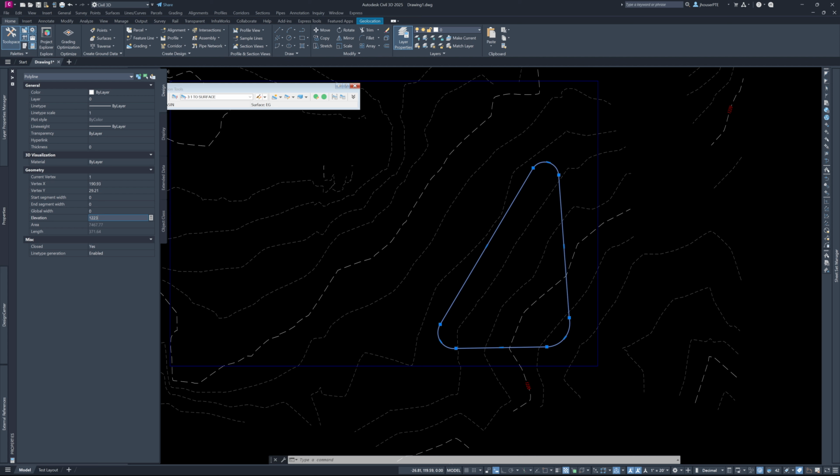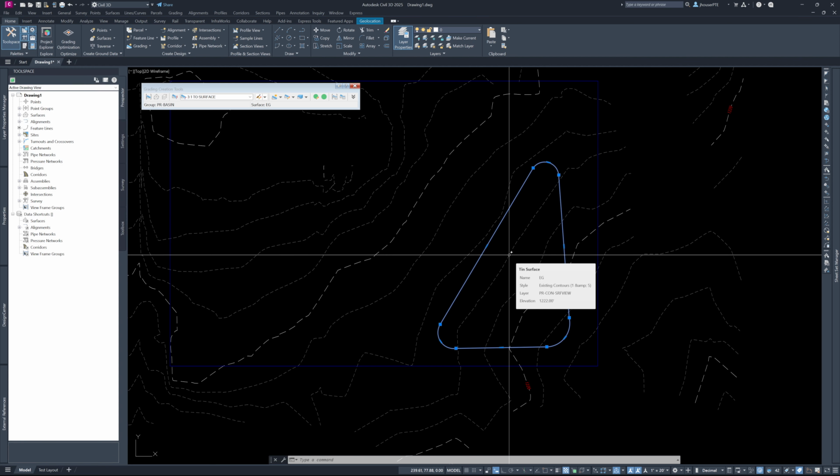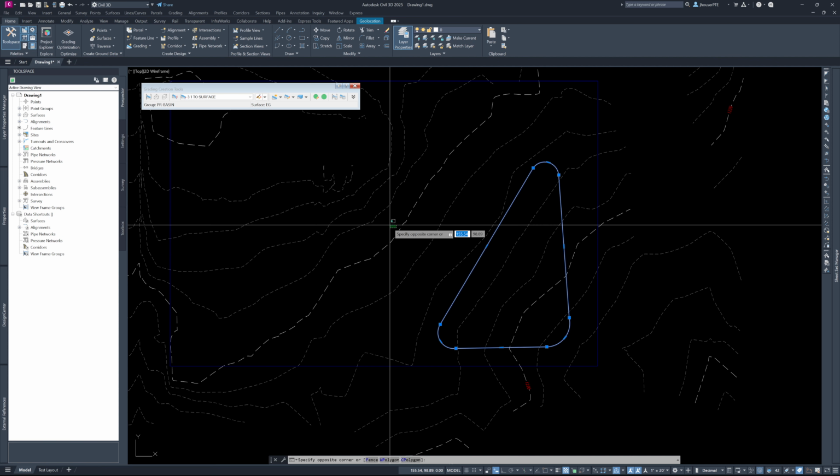This allows the contours to be rendered a little bit easier. So even if it's a 0.05, this should work really well and show your contours properly whenever we go to build our surfaces. If you do it right at the actual even elevation, it can cause problems with contours crossing over the berms and such. So I'm going to set this at 1223.05. And there we go. Okay, so we have our elevation.